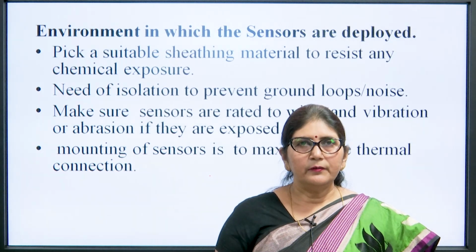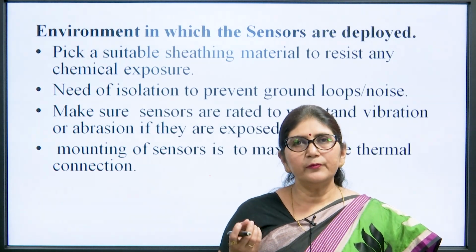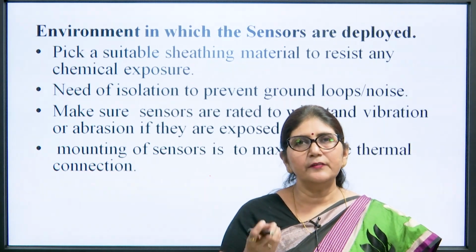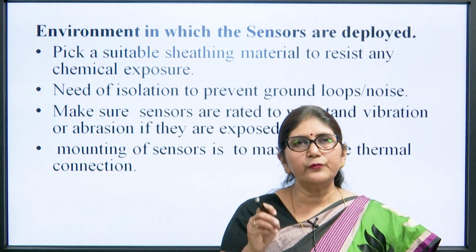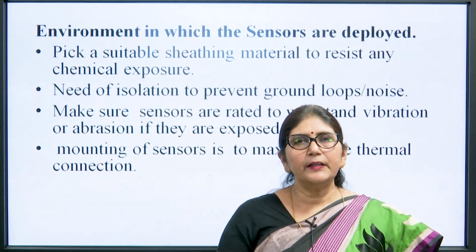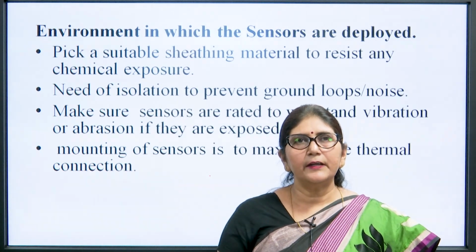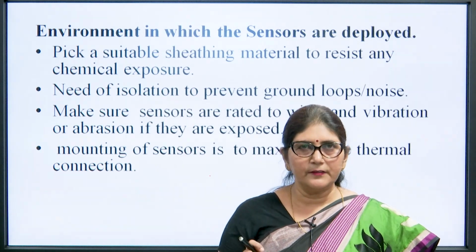Then the environment in which the sensors are deployed. We have to take care of which sensor we are using. If the sensor is exposed to a chemical environment, we have to cover it with metal sheathing material to resist the chemical exposure of the sensor.